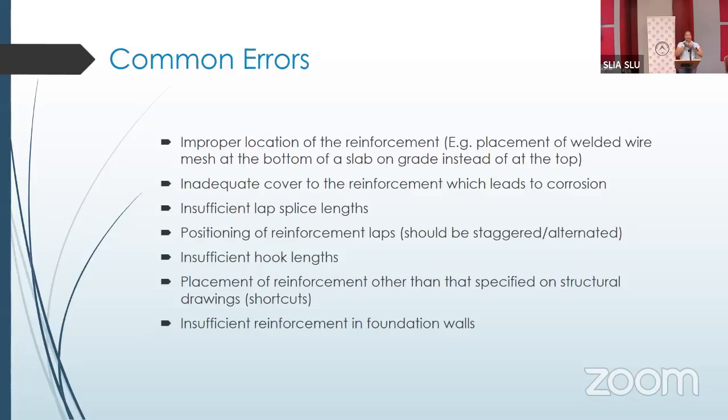There's a reason why we specify those lap splices. We need whatever stresses build up within the concrete to be able to transmit properly to the supporting members, and the supporting members down to the other supporting members. So for example, we're going from the slab to the beams, beams to the columns, columns to your foundation, foundation to the bearing ground. Those lap splices are given for a reason. So when you put less than what we actually specify, it means that you don't have enough length for those stresses to actually transmit fully and completely to the other members.